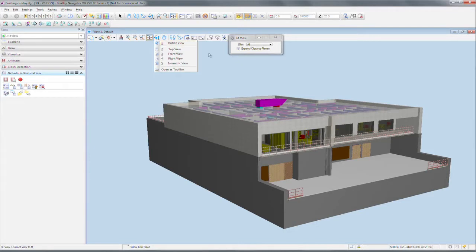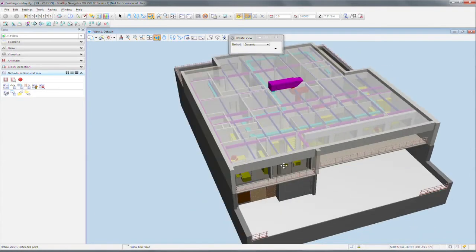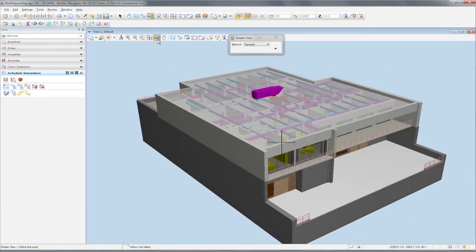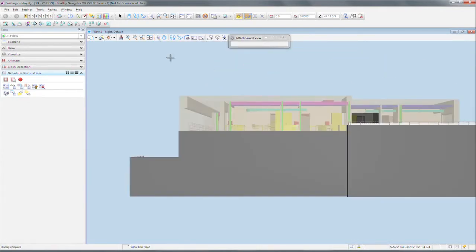Now, this is another one of those icons. If you click it, then it puts it in the mode to do whatever is in that little box there. And that's rotate the view. If, conversely, you click and hold, it gives you the different options of what you can put into this window on the screen. I can put just a top view if I wish, and then that changes the icon. Notice, see the little gray on top? That means we're looking at a top view. Or I can click and hold and look at a right view. Or I can put it back to the isometric view.